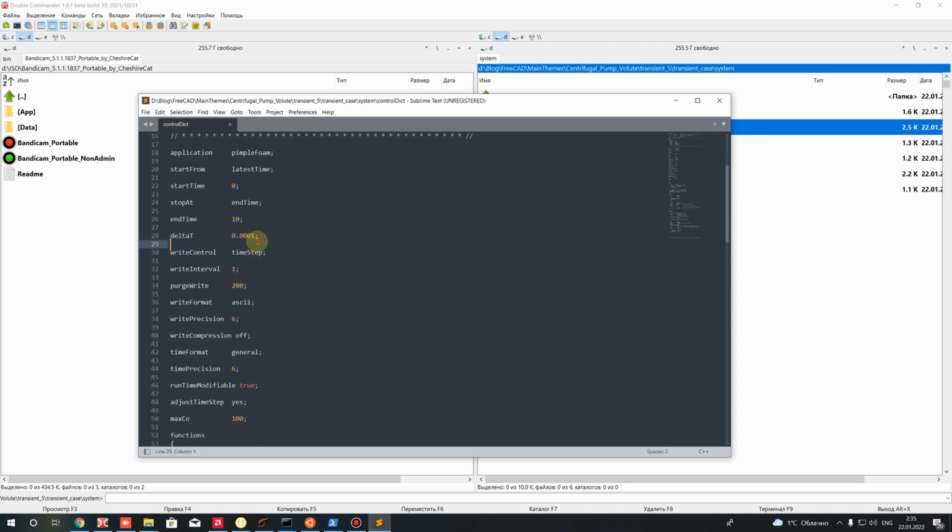Here we use the physical time, and the time step is delta t in seconds. For this value, it's not a constant delta t, because we use the maximum Courant criteria. I set 100 as the maximum Courant number and activate these changes with delta t. It means the first iteration will use this value.